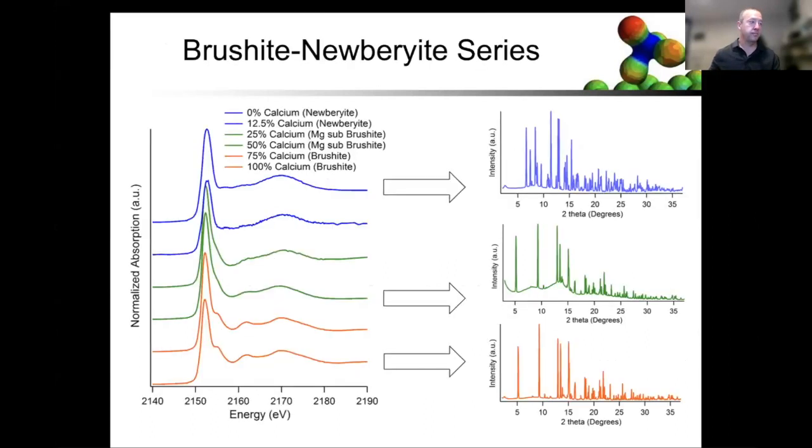And when that's done, you actually could see dicalcium phosphate, that brucite, which is a fairly poorly crystalline material, actually has the ability to incorporate a large amount of magnesium in its system without its structure changing too much. And when that happens, it certainly becomes even less crystalline. You see here in the green region is kind of that intermediate phase.